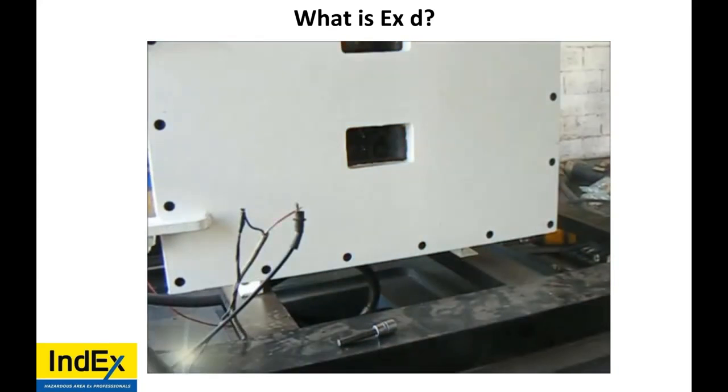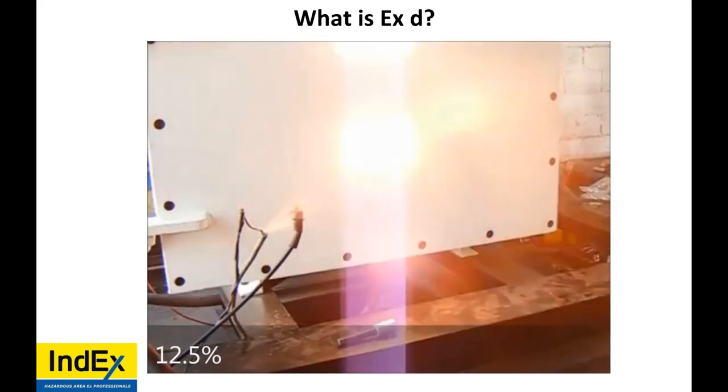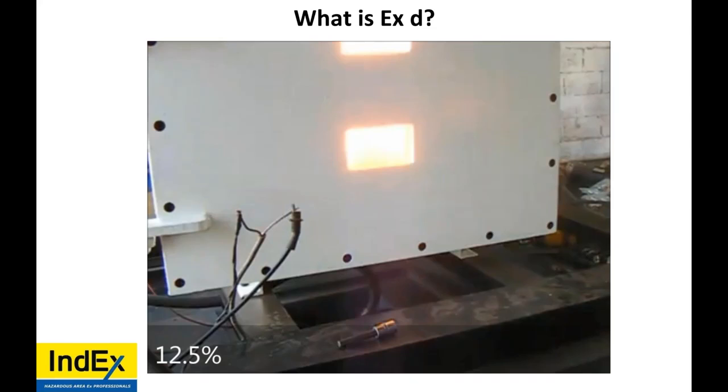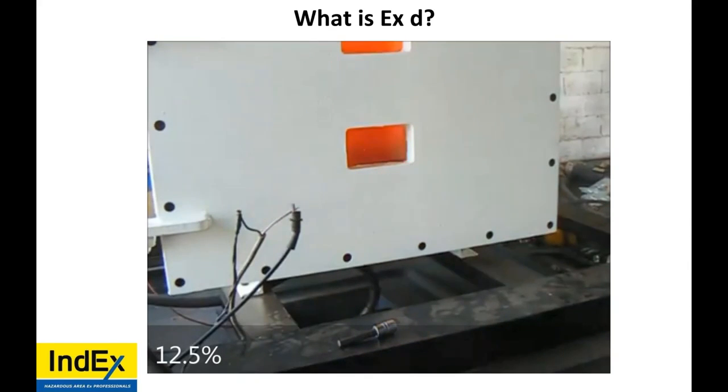So it's important to maintain its protection technique. Have all the bolts in, use the proper glands with the proper cable, or use barrier glands, and use high quality cable. If your cable's not circular and compact, this could happen.